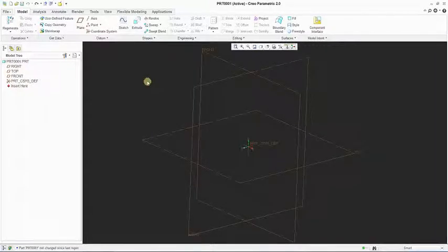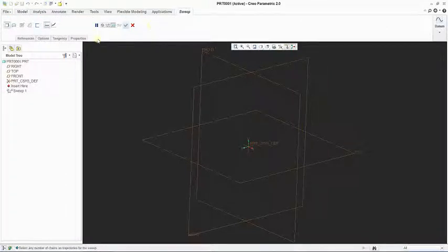So let's say, what is basically trajpar? When you talk about trajpar, it's basically a variation that can be created for a section using a relation. We would go through a few of the processes by which it can be done, and some of the complicated examples that we can see in this place. A simple example that we start with would be a simple sweep. Basically we're going to do sweep most of the time.